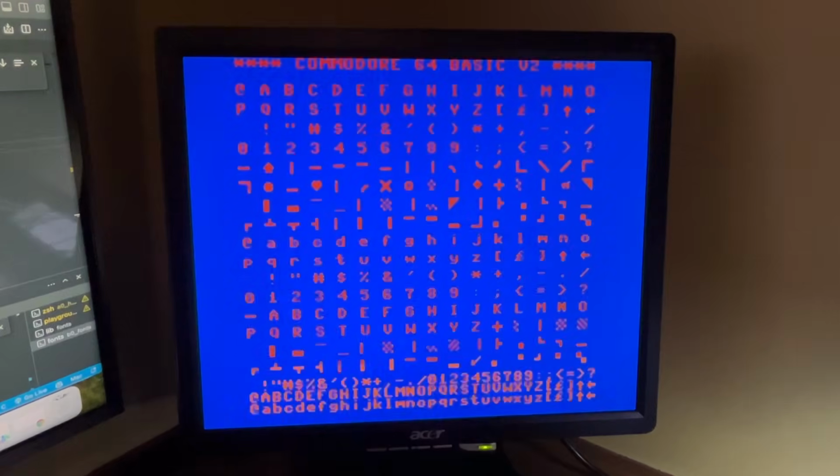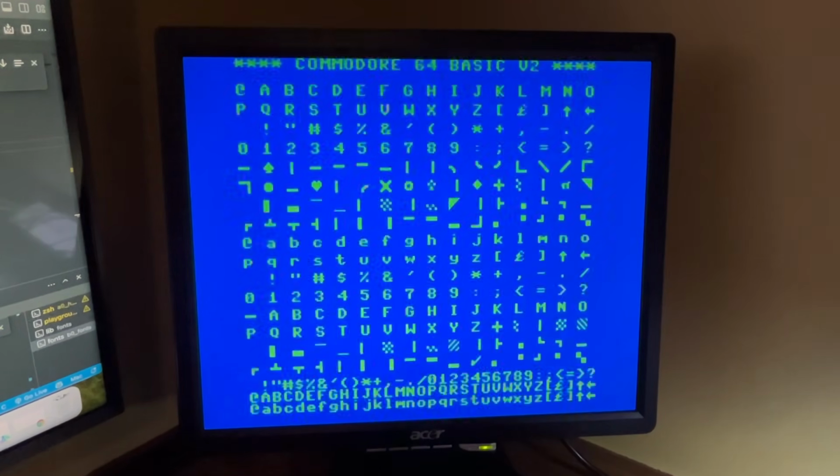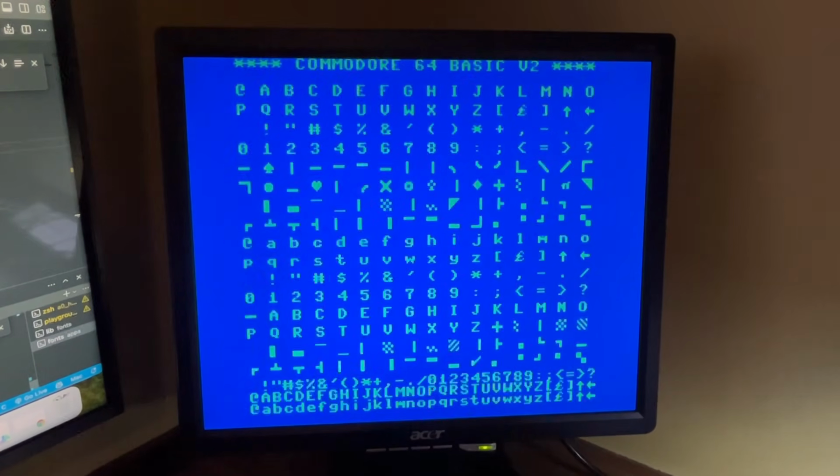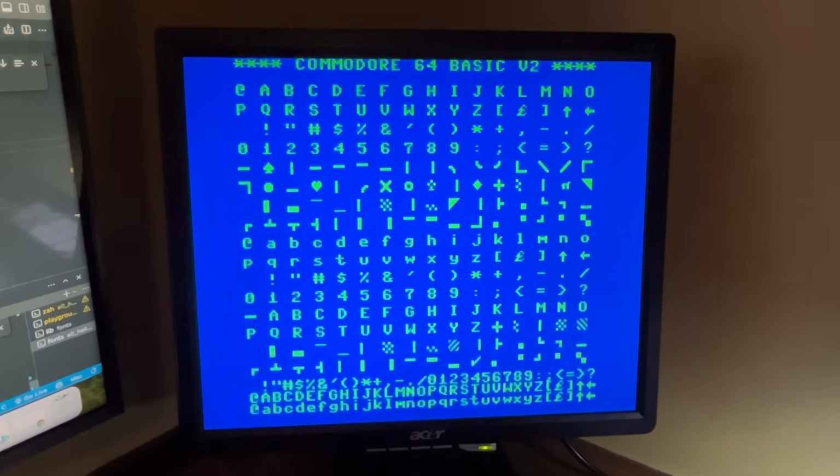So our final demo is for graphics generated text. This is not a text mode. I have imported the Commodore 64 character generator so that you can draw text on the screen. It is not the most efficient way to draw text. It's implemented in the GFX library rather than in the VGA library itself. So there is a way to draw it, and this demo also shows off the fact that with single-bit graphics we can color or change the palette in real time and will cause a flashing of pixels on the screen.